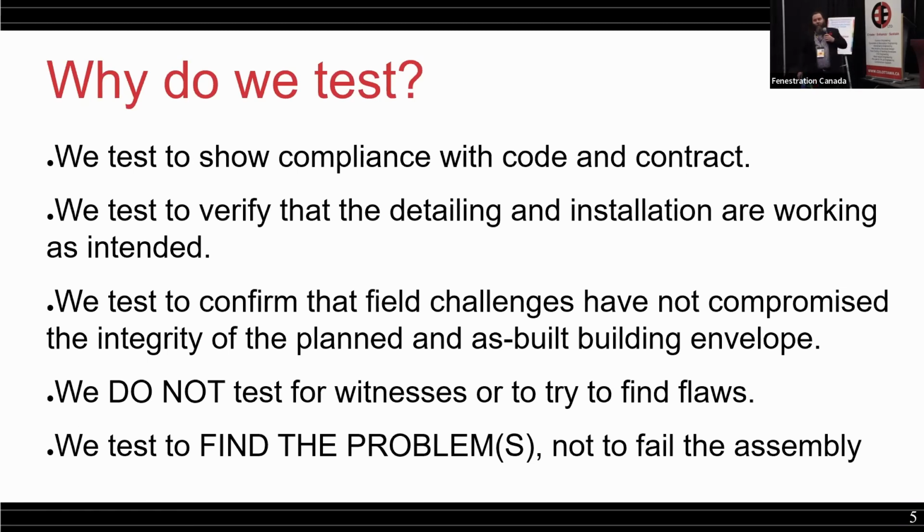Okay, so why do we test? We test to show compliance with the code and the contract. We don't test to force things to fail. We don't test to try and make somebody have a problem or a bad day. If a consultant shows up and does their job properly, either your window and the assembly, one and or the other working together, failed or passed. And it should be done to a very simple, competent standard. It should be predictable, and you should know in advance, most likely, whether you're going to fail or not.